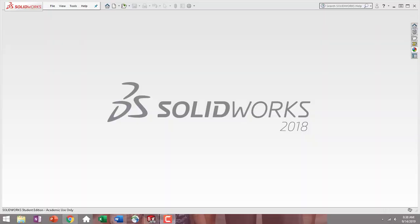Hey everyone, welcome back. Today I want to make a tutorial to go over our Milestone 2 where we discover blocks and configurations. This project milestone will require you to practice how to do your SolidWorks extrudes, which include bosses and cuts, shell features, sketch relations, convert entities, linear feature patterns, equations, global variables, configurations. We'll also learn how to create derived parts and change the appearances of our parts.